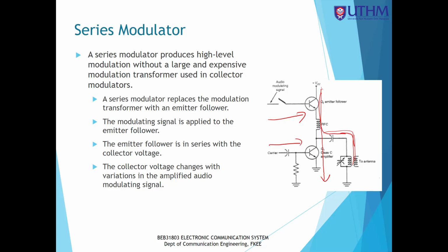So when the voltage at the base is less than the transistor threshold, the current cannot flow from VCC to the ground. Instead, at that point, the LC tank circuit will discharge and resonate to produce the missing half cycle of the negative cycle of the signal.